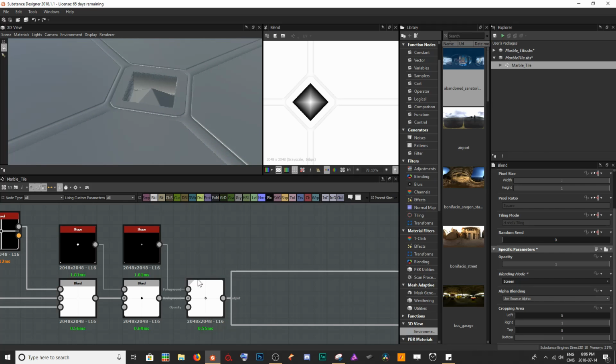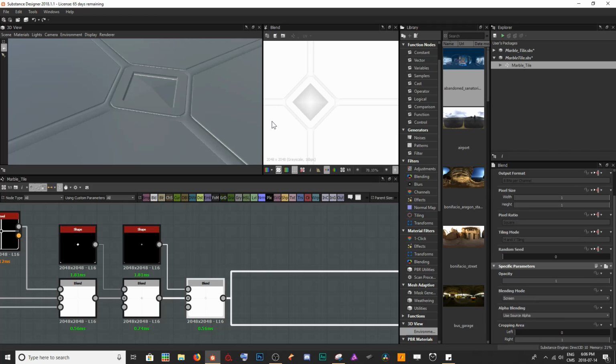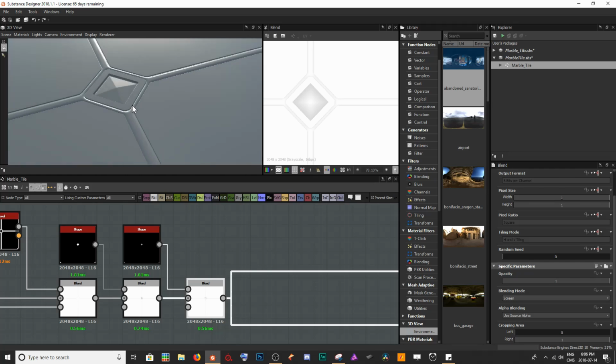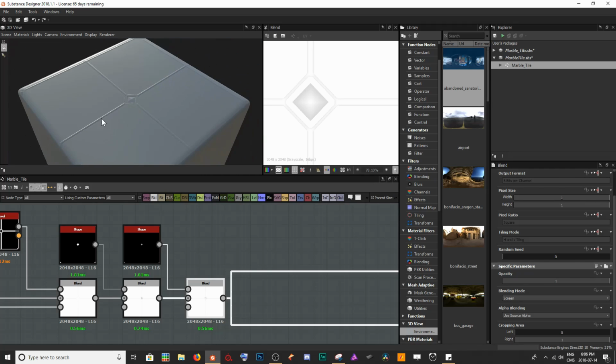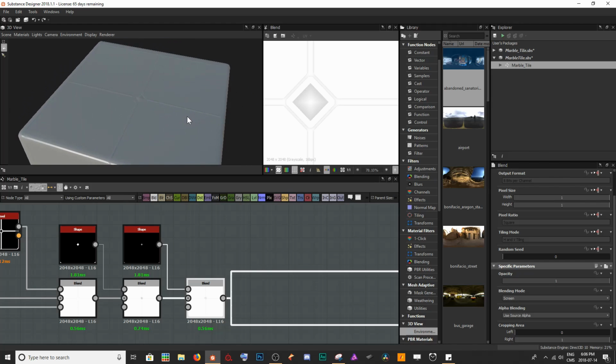And so with that, what I want to do is come back to our blend here where we cut away, and decrease the opacity on that guy. Bring that right up towards the top there so that it's not as drastic of a cut as it initially was. And so now we get a nice little pattern right in the center design of our tiles here, and it's going to be a nice focal piece for our material.